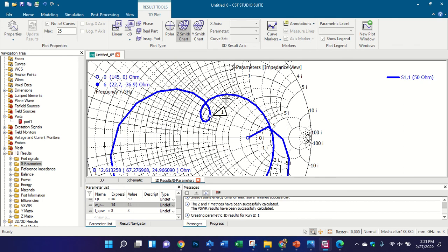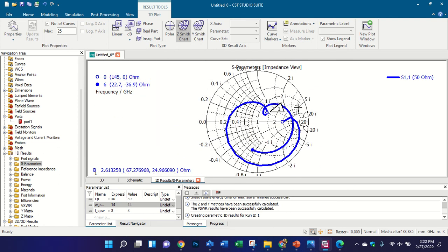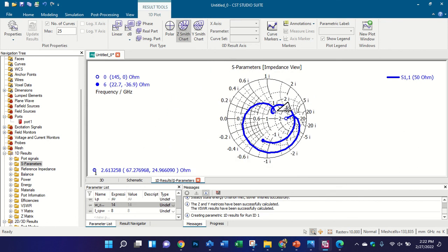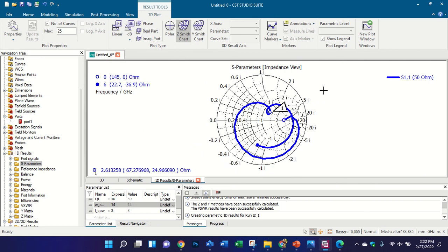Suraj, I think we can observe the capacitive and inductive phenomena of the antenna through the Smith chart. If it is resistive, it means it has the maximum transmission of the electromagnetic waves from this band. But if it is inductive or capacitive, it can show some reflection loss, or maybe some transmission loss.